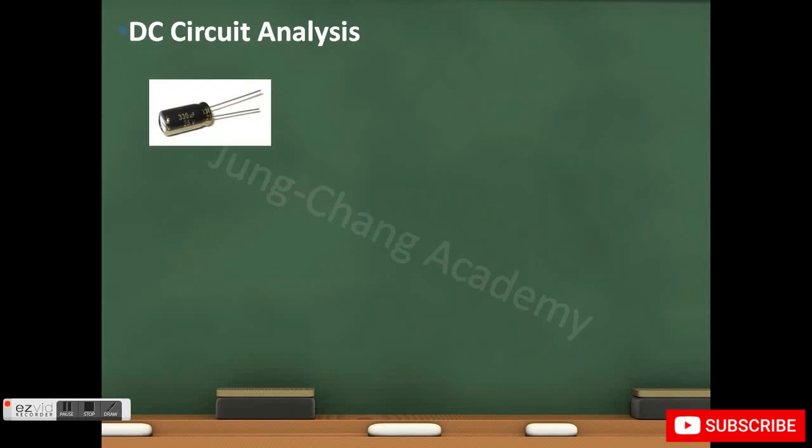As for a capacitor, the current is equal to the change in voltage times the capacitance. Since a DC supply has a fixed voltage, the current flowing through that capacitor will be 0. In other words, the capacitor will look like an open circuit.